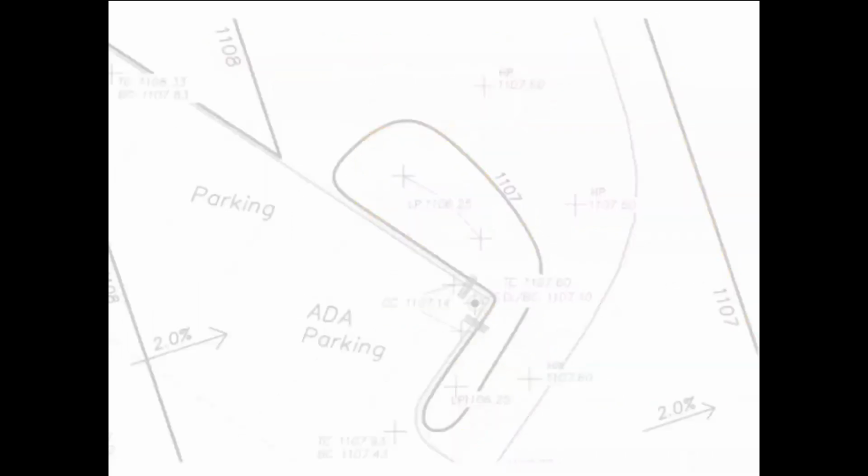So we start on this drawing by having two curb cuts. These two curb cuts are uphill from the drop inlet. And it's important to notice that we actually label these, we can label them what we want, with one spot elevation, because two curb cuts going into the same retention area must be at the same elevation. Again, they must be at the same elevation, whether they're next to each other or not. You could have a curb cut on the opposite side of your bioretention, but if you have two curb cuts going into the same bioretention area, they have to be at the same elevation.